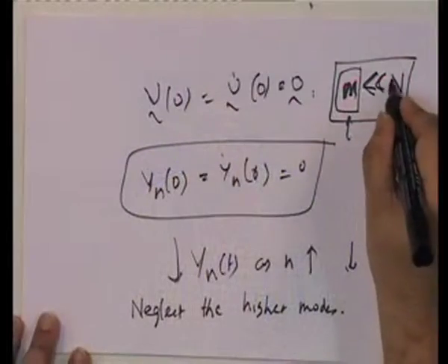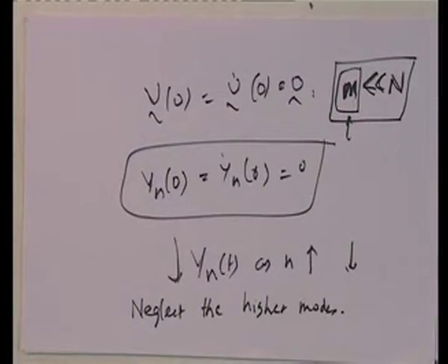Once I do that, we still have not talked about damping; we only said proportional damping works. We will have to see how we can get proportional damping. We will look at damping in a little bit broader sense for multi degree of freedom system problems. And finally, we will look at some examples to show you that indeed m is significantly less than n. So, that in essence is what I shall be looking at, dynamic response of multi degree of freedom system problems.